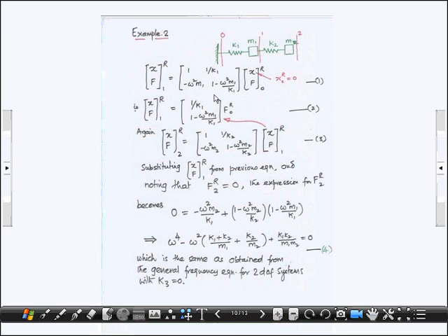So when you connect, let me now relate with the transfer matrix the state at station 1 with that at 0. You know x_R1 will be equal to 1 by K1, minus omega square M1, 1 minus omega square M1 by K1. This is the transfer matrix that relates to the state at 0. But we already know the displacement at this point, x_R0, is 0, and once you do that, you will get x_R1 will be, when you multiply this by 0, 1 over K1 times 1 minus omega square M1 by K1 times F_R0.